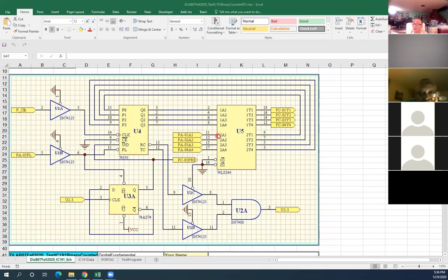And also pin 19 will control the other group, pins 11, 13, 15, and 17. Okay? If pin 19 is 0, pin 9 will equal 11, 7 equals 13, 5 equals 15, and 3 equals 17. In this case, they routed both.